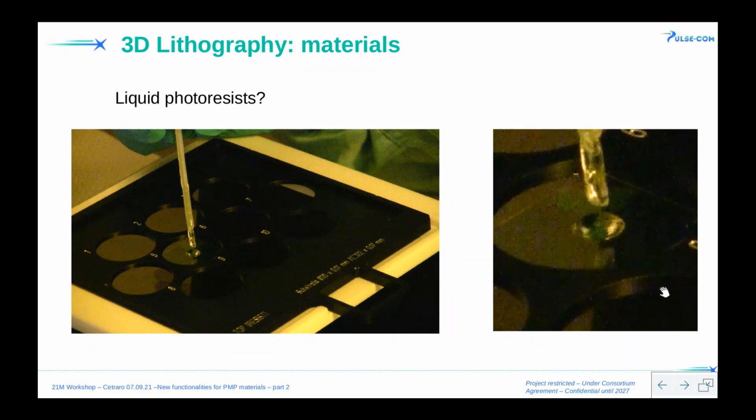It's very different if you have used UV lithography, for example. You know all the processes that you have to do beforehand. You have the photoresist. You have to have a good surface quality. It has to stick. It doesn't have to be hydrophobic. It has to be hydrophilic, and you put it through spin coating and baking and all of that.